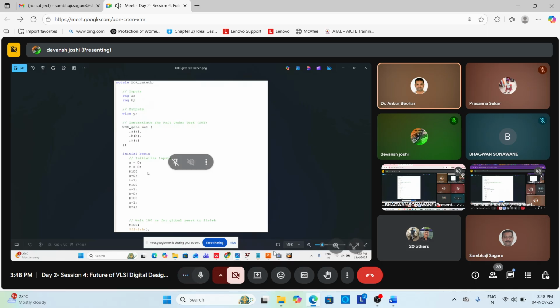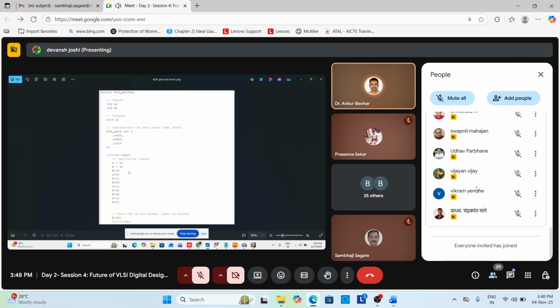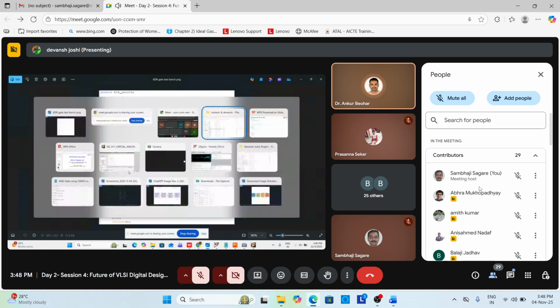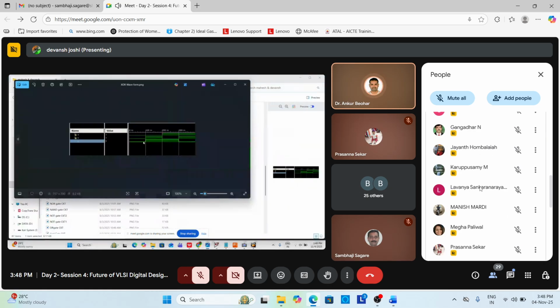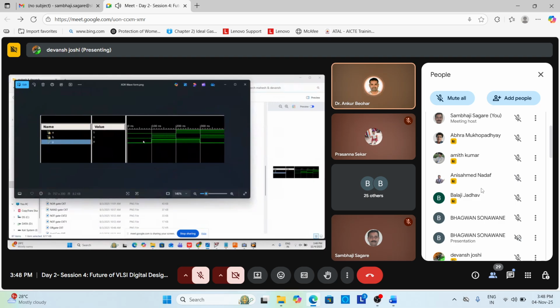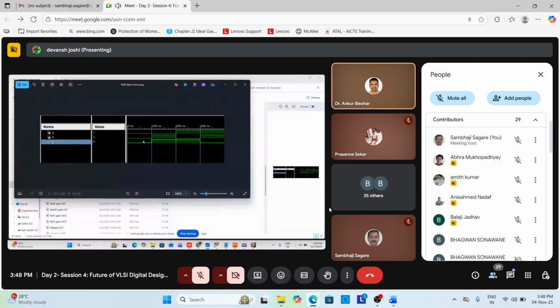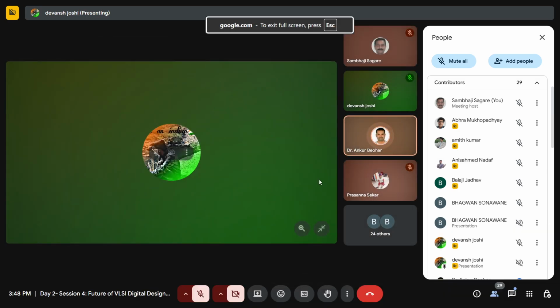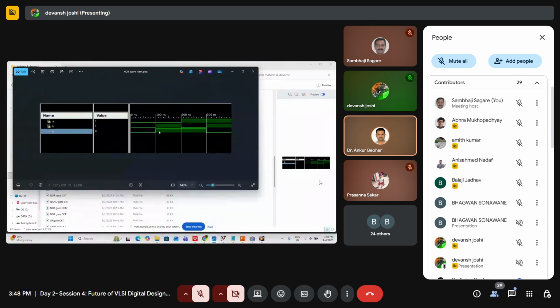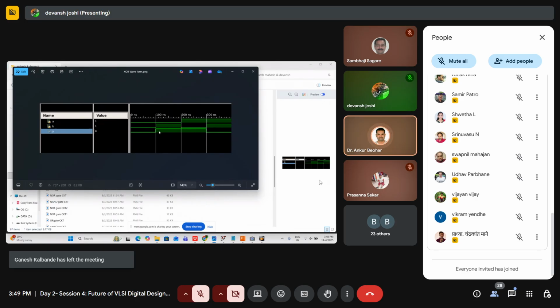Okay. So here we have an XOR gate. You can see directly we have opened the process here in Xilinx. Now we have given the two inputs A and B, which you can give for the analysis of the output waveforms. Once after that simulation, we have the output waveforms for the XOR gate. So XOR, we know very well, the decision is like A bar B plus A B bar; however, the output is one if the two inputs differ. So here we have given two inputs, here XOR.